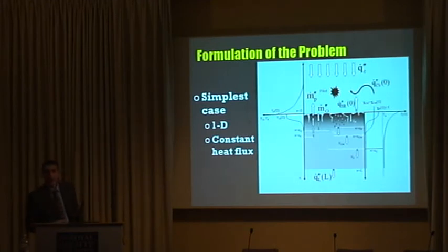The truth is that that is the definition of the standard, but this is the reality of the ignition problem. Now, you might wonder what all these little things are here, but these are all the things that are happening. From the production of fuel, the diffusion of oxygen, distributions of oxygen concentration in depth, the distribution of fuel on top. You have convective boundary conditions, you have surface irradiation, you have all these other things, even heat losses to the back. And this real problem, even if I keep it one-dimensional with a constant heat flux, is a much more complicated problem than the one that the standard described.